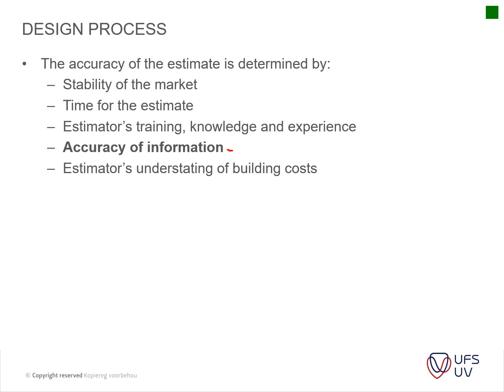We actually saved a lot of money because the tiling area was such a large area. We could rather put in the PVC expansion joint instead of the stainless steel one, and we still got the same look and feel by just looking at the color of the PVC one that we put in. So those are options that one can look at when you do your estimation.